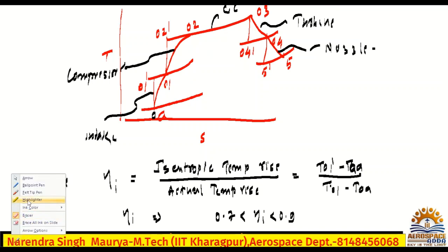One thing I want to add here. Okay, this is 0.96, because the diffuser is a non-rotatory part. Compressor and turbine are rotating, so obviously the diffuser will have more efficiency compared to compressor and turbine. We need to be careful, because intake, diffuser and nozzle do not have a rotatory part, so obviously that efficiency will be more.